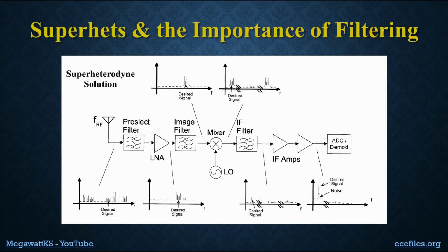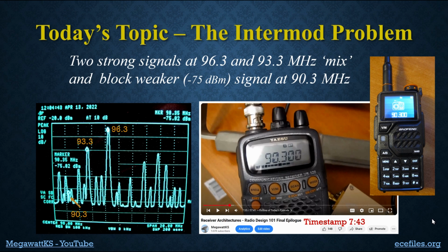And just to whet your appetite for what we're going to talk about, why that radio could perform better, the reason is these filters before the mixer were sharper. They were more narrow in bandwidth than in the other radios. We're going to come back to this slide later. But there was one other problem, and this problem exists in all modern radios except ones like in a car that have a lot of power consumption and are able to deal with it.